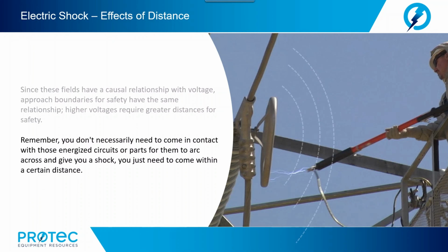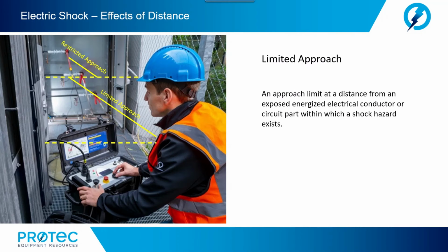Now remember, you don't necessarily need to come in contact with those energized circuit parts for them to arc across and give you a shock. You just need to come within a certain distance and interact with that electrostatic field. So for safety, we have what are known as approach distances.